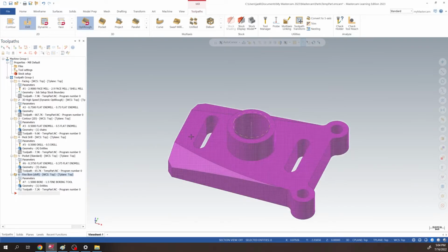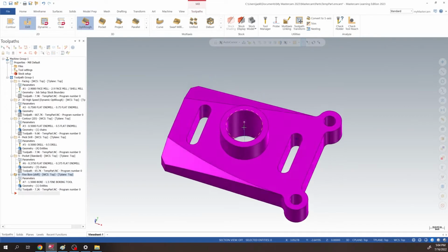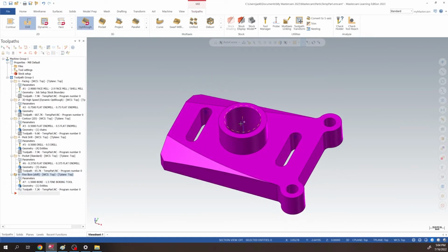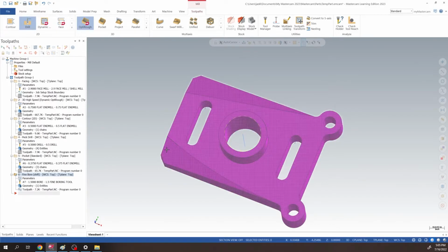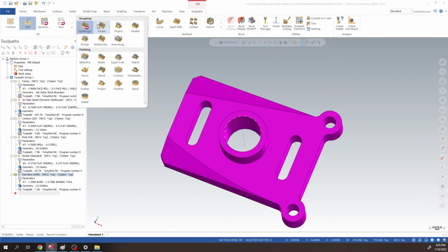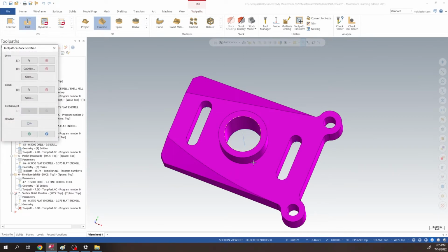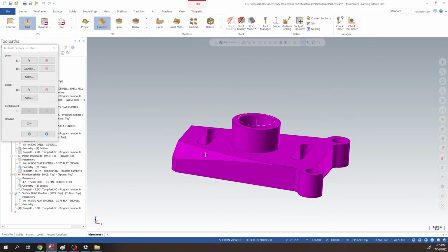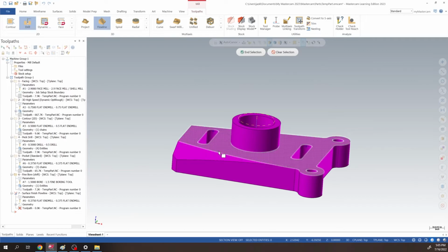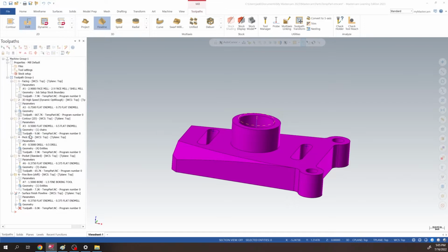And then for the next thing that we can do, we could do our 3D surfacing here. So I'm going to go down and use flow line. And let's start with this front surface. For check surfaces, I'm just going to select the top here and click OK.